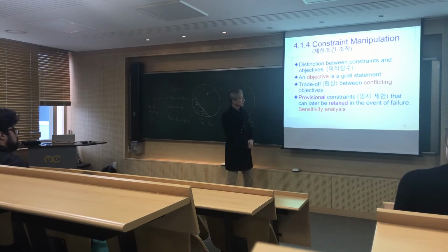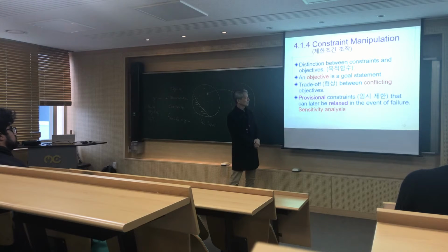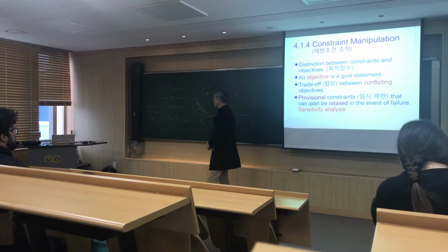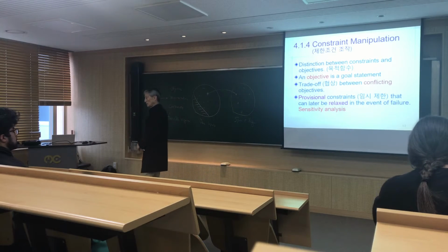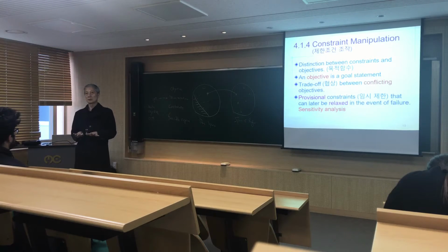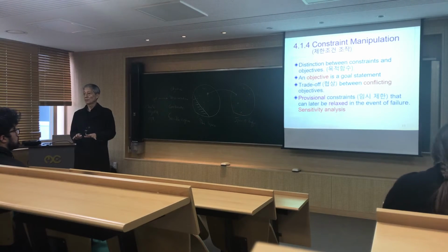Provisional constraint, that is a tentative constraint that can later be relaxed in the event of failure. So we call this sensitivity analysis in optimization problem. Sensitivity. If I lower down the regulation for stress level by 10%, then what can be the optimal design changes?